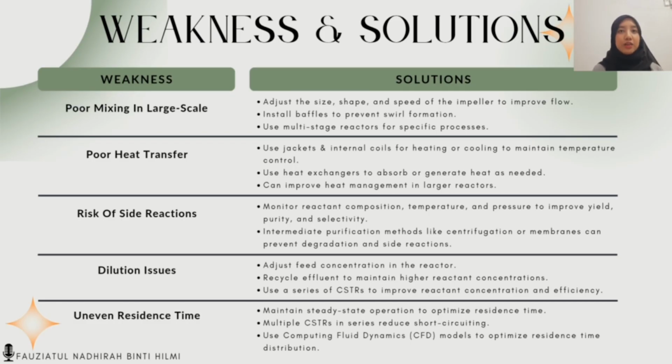Next is dilution issues. It can be solved by adjusting feed concentration in the reactor or recycling effluent to maintain higher reactant concentration. A series of CSTRs also can be used to improve reactant concentration and efficiency.